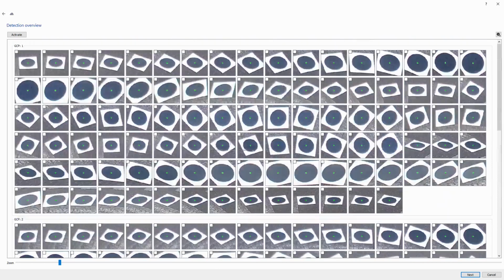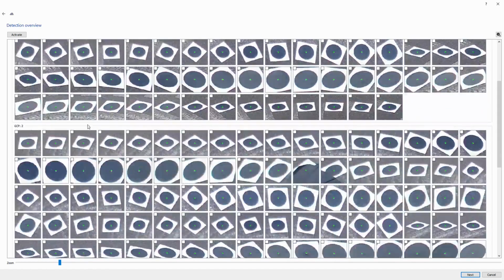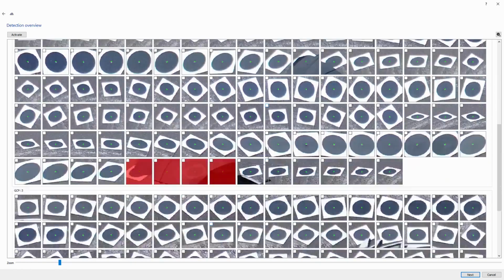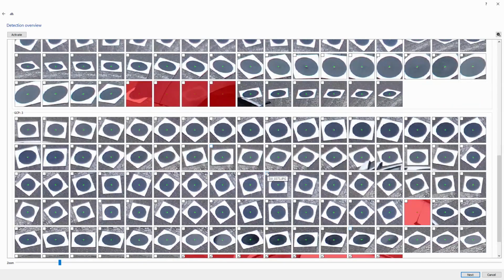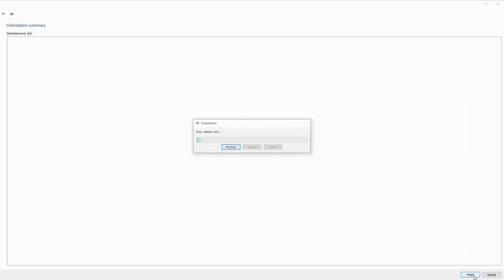And what we can see here is actually ground control point 1 is on, let's say, 50 images, and more. Ground control point 2 the same, on at least 15 images, and so on. And in this way we orientate all images really accurately. I'm satisfied with this one.